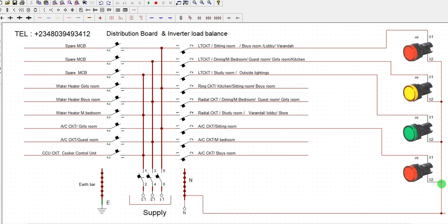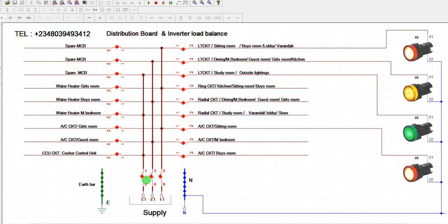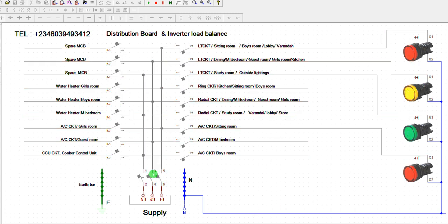All right, now let's test the distribution board. These are the 3 lighting circuits that I have. I define them as my essential load because I want to feed them to the inverter as well after this first step. The next step is to break them up and interface with a relay device. So let me assume that the inverter will also power one of my air conditioners. That's why I want this one on. So let's first of all energize my normal default setting of the distribution board. So I put on my DB. All right, look at my load on. So my DB is working now. I shut down the DB, the power goes off.